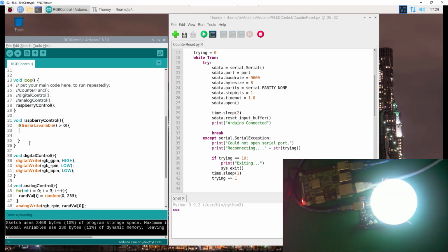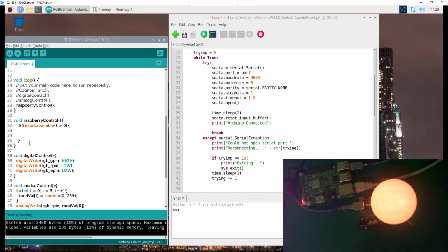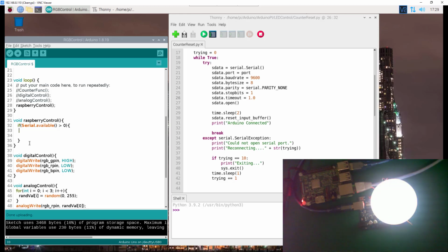that is coming from the serial, and we need to read it until we reach the end of line. Okay, so that will mean we have read the whole message, so we store it. Okay, I've explained this in the previous tutorial, but before we do that, we have to create a variable. A variable must be of type string. So I'm going to just say messageFromPi. Okay, so this is a message from Pi, and the messageFromPi is Serial.readStringUntil.